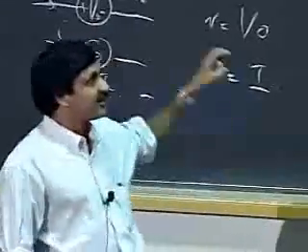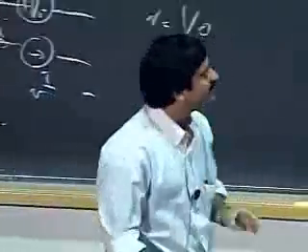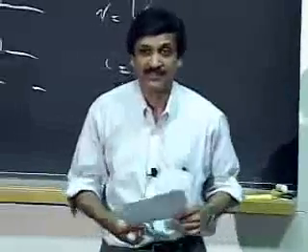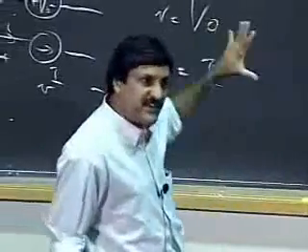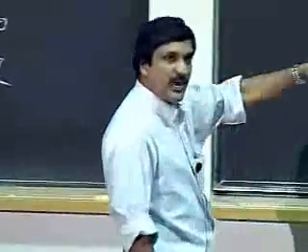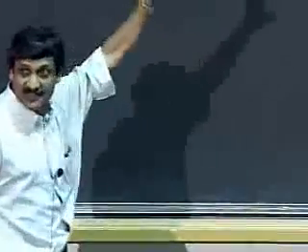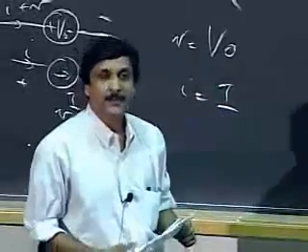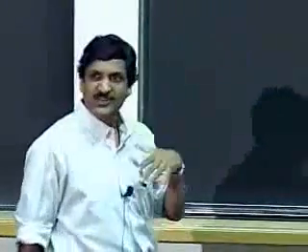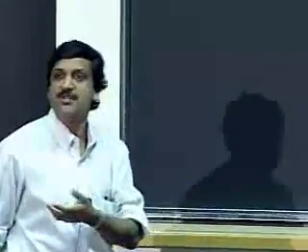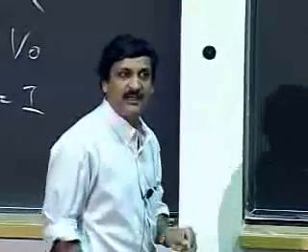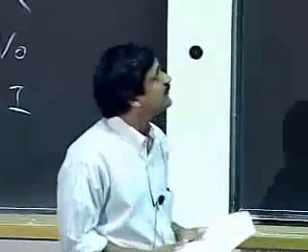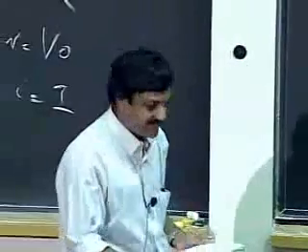However, notice that this is quite a grubby method. It's quite grungy. I get 12 equations, and it's quite a pain, even for a simple circuit like this. However, suffice it to say that this fundamental method that is just one step away from Maxwell's equations simply works. So what we'll do in the rest of this lecture is introduce you to a couple more methods. One is an intuitive method, and another one, called the node method, is a little bit more formal, but is much more terse than the KVL, KCL method.